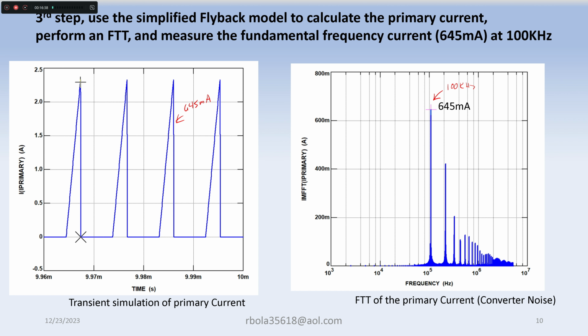That would be the fundamental. Now remember, this is what's in the primary of your converter, and you want to limit no more than 1 milliamp into the bus.